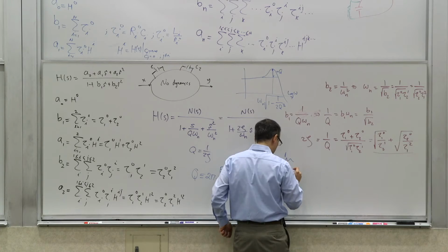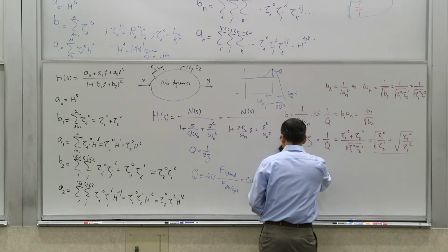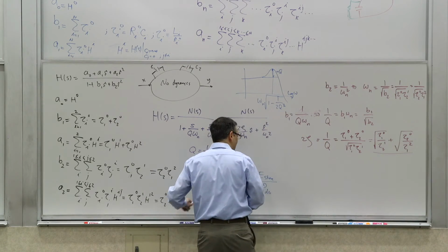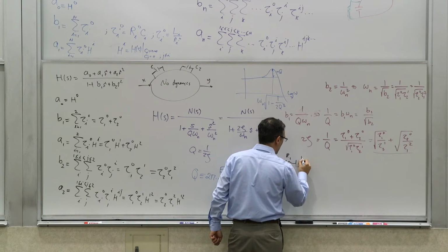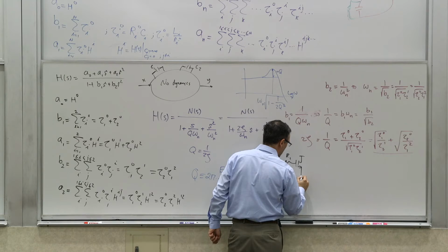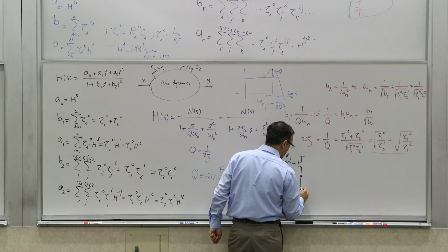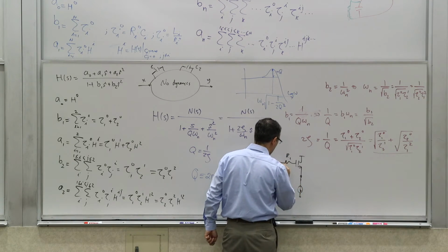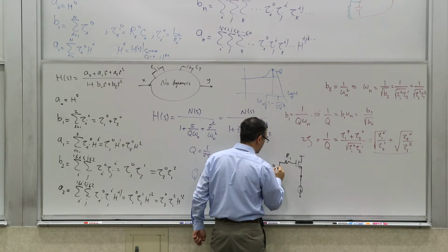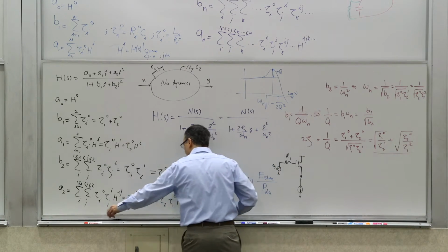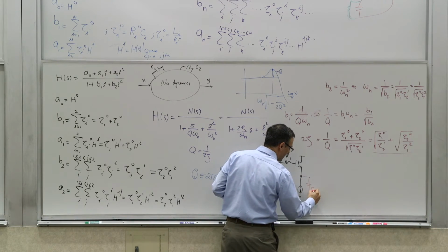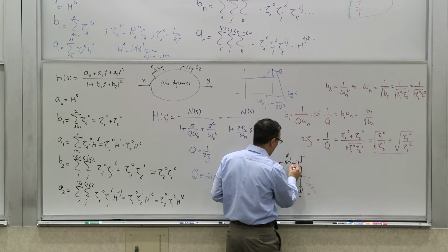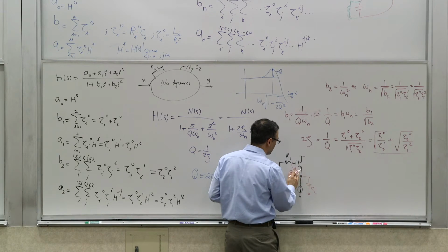Say you just have R1, the input resistance, a resistive load and a capacitive load. You have this device, and then this is your output, with a current source, and this is V in. Then you have a capacitor CL, and a capacitor C pi. Let's forget about C mu for now.